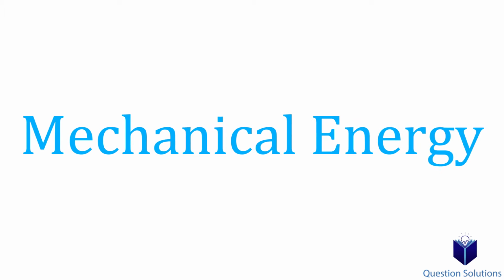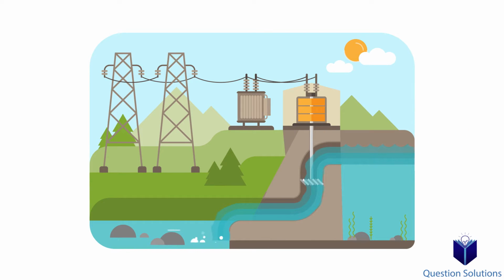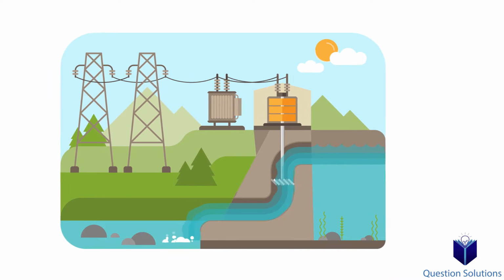One last thing we need to talk about is mechanical energy. It's a form of energy that can be converted to mechanical work. But what we're interested in is how the pressure of a flowing fluid is connected to mechanical work. For example, when water goes through a turbine, what's happening is that the turbine extracts mechanical energy from the water by dropping its pressure. Pressure itself is not a form of energy, but if we look at a pressure force that acts on a fluid through a certain distance, then that creates work, and it's called flow work.